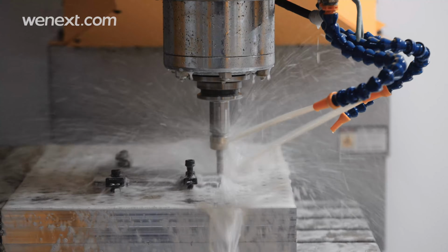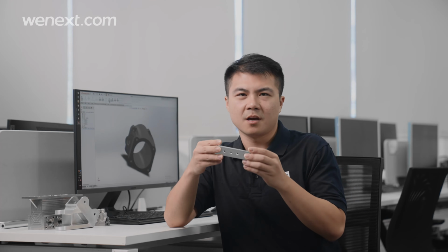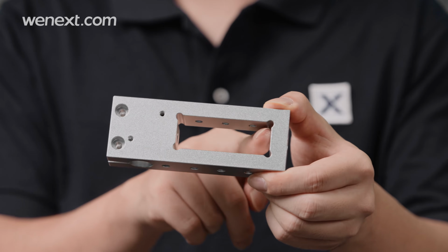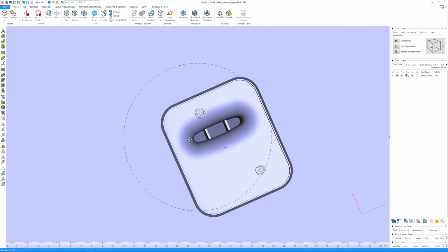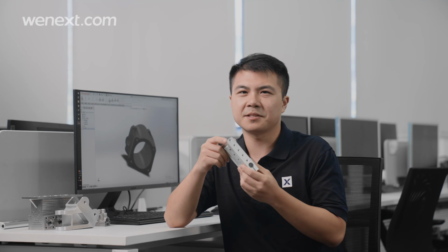3-axis machined parts. However, since 3-axis machines can only cut parts along 3 axes, it is usually used for cutting parts with cubic geometries. If the part has 6 sides to machine, the operator has to flip the blank and change fixtures manually. Besides, it is difficult for 3-axis to machine parts with unconventional shapes and deep, narrow cavities.